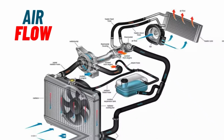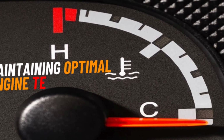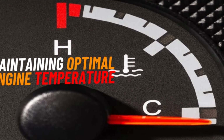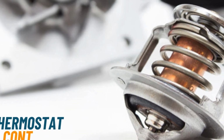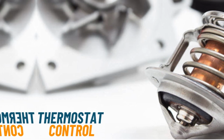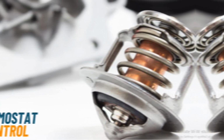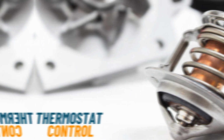The next point we will discuss is maintaining optimal engine temperature. Let us start with temperature regulation. Number 1. Thermostat control. The cooling system includes a thermostat that monitors the engine's temperature. When the engine reaches a certain temperature, typically around 195 degrees Fahrenheit or 90 degrees Celsius, the thermostat opens, allowing coolant to flow into the radiator.